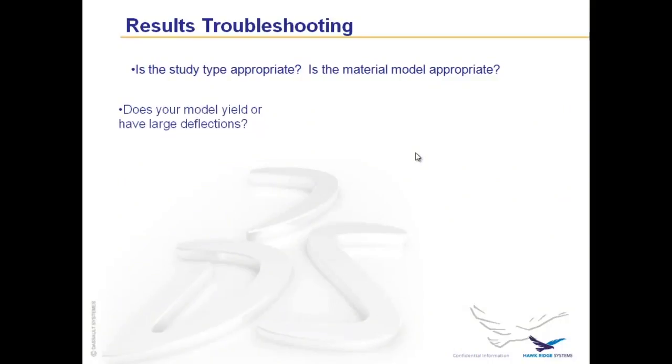Now, going back to, is your study type appropriate? With a linear static analysis, you're assuming that the material behaves linearly through its entire range. Even if the model has yielded, if you're using that linear static analysis, it's still going to assume a linear stress strain curve even past yield.